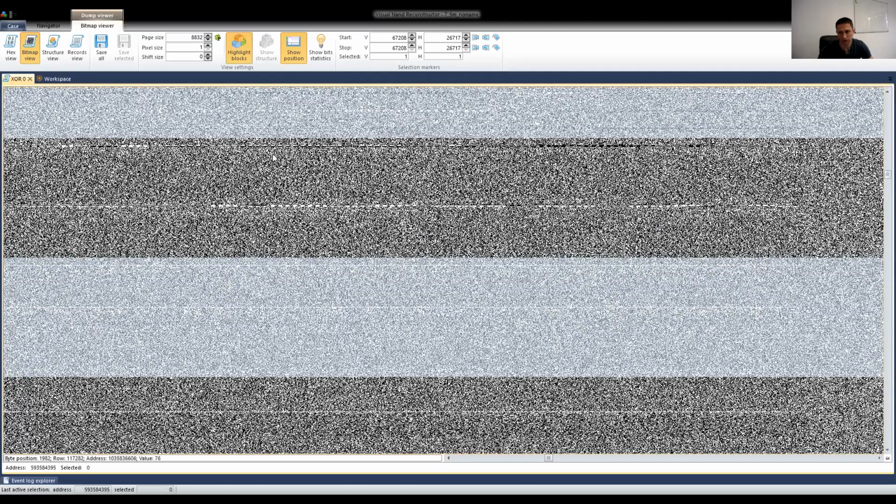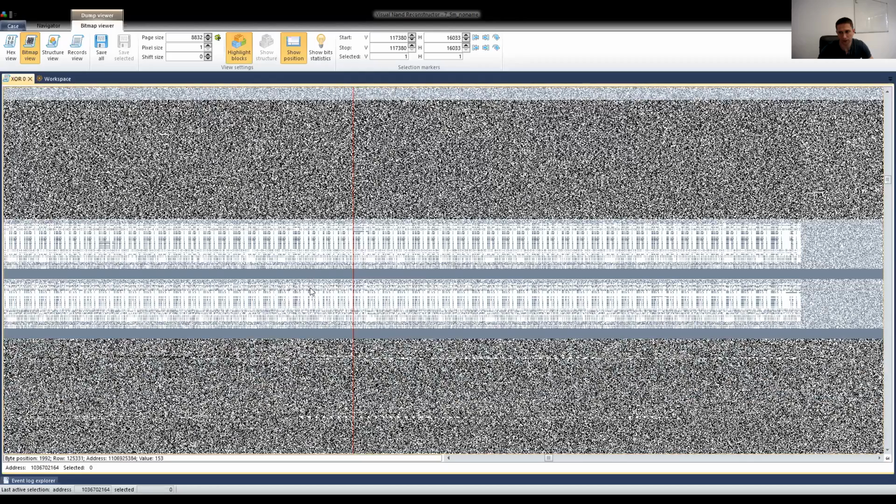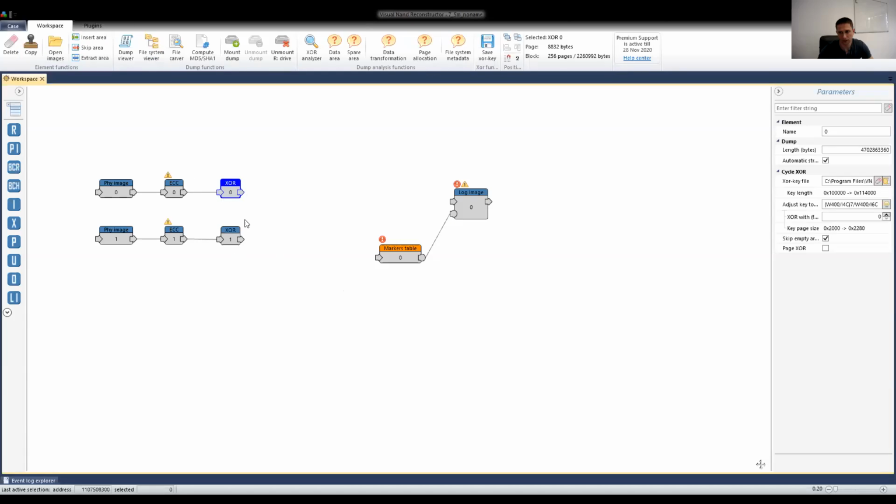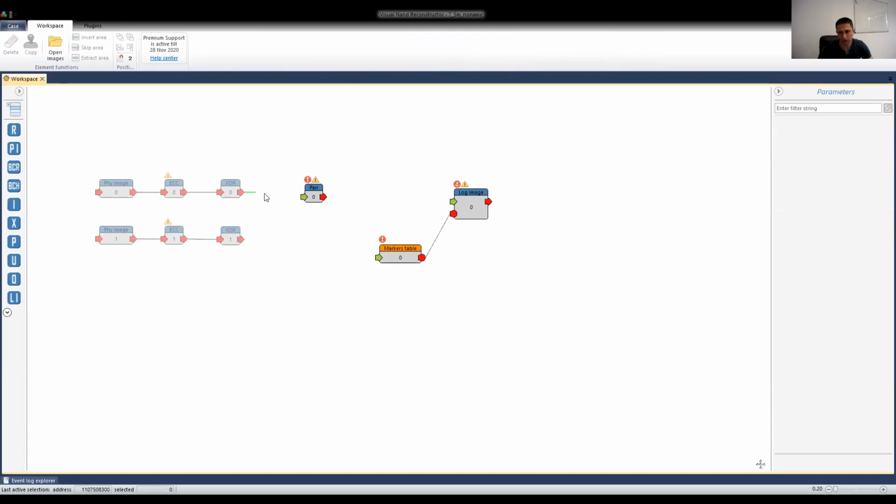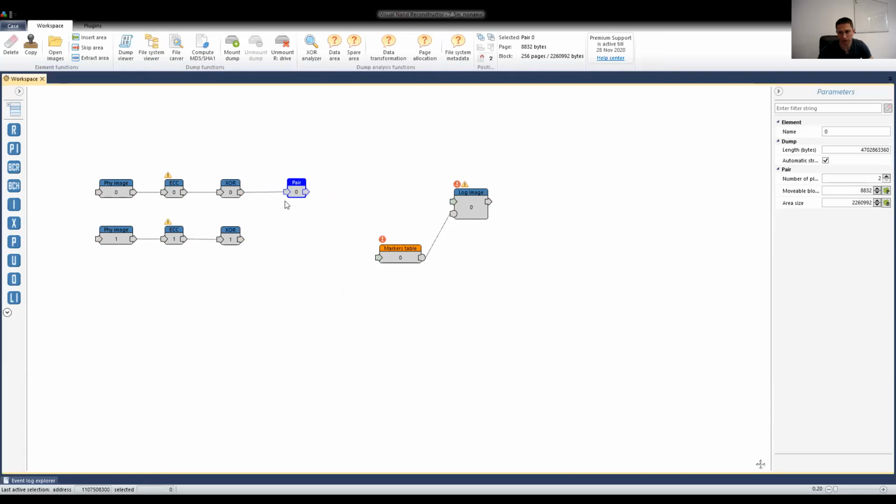And since we saw two repeatable patterns, for example, here it's quite recognizable. So we have one line in this part, one line in here. And since we have just two lines, recognizable ones, we know that this is a two planes case. Another repeatable pattern. So pair should be used. Okay, so we know that we have two planes here. We know that block size is correct. Virtual block size is correct. So all we need to do, just drop here pair, and that's it.